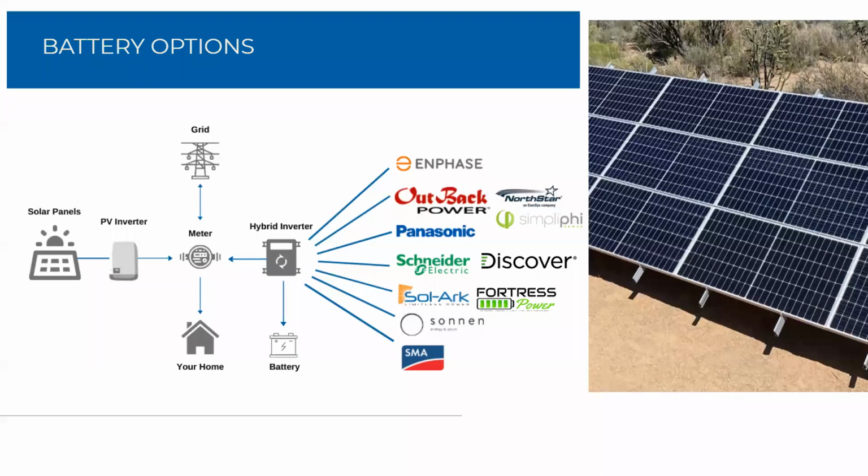So like, let's say Enphase, I think off the top of my head, they have like self-generation mode, emergency backup mode, and time of use mode. If you operate in time of use mode the majority of the time, just make sure that you enable it so that if a weather alert is telling your Enphase system a storm might be occurring, why don't you switch from time of use to emergency backup mode?